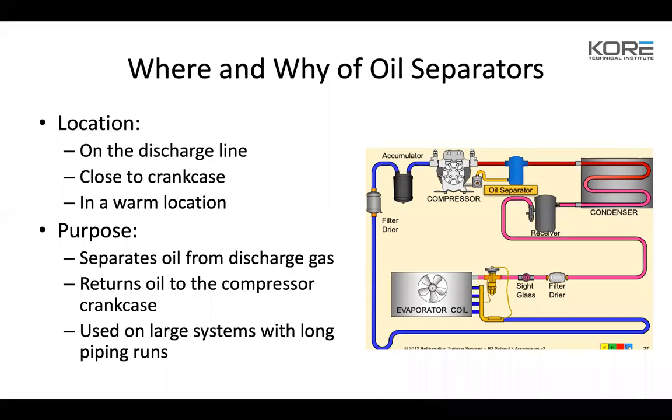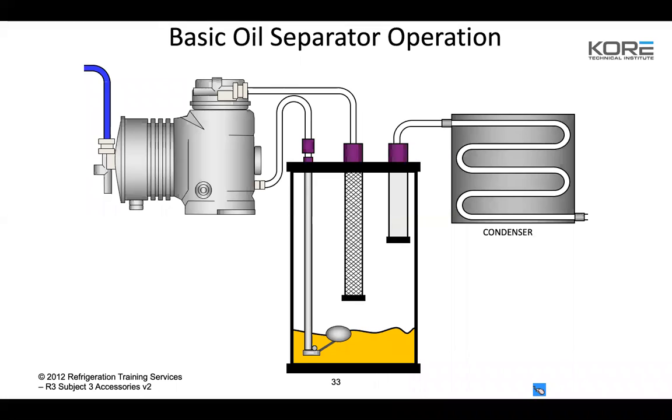Anywhere that your oil is touching on your rack systems, you should always be touching the separator, touching the oil lines, and then touching the oil pump on the front of the compressor. It should always be warm. Anytime you're getting cold there, you've got liquid in your oil, and that's a bad thing. You don't want that stuff to be cool or cold at all. So, oil separators, for you rack guys that are on here.